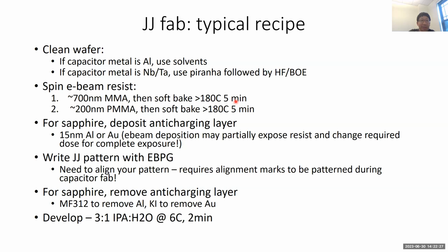Cool. So another couple of questions on oxidation. Is the oxidation done in a load lock or in the actual main chamber of the deposition system? That's going to highly depend on your specific system. In our lab, we have a 3-chamber deposition system: a load lock, a deposition chamber, and an oxidation chamber. We do our deposition in the deposition chamber, then transfer it to the oxidation chamber where we do the oxidation, then transfer it back into the deposition chamber for the second layer of deposition, and then move it back to the load lock for unloading.